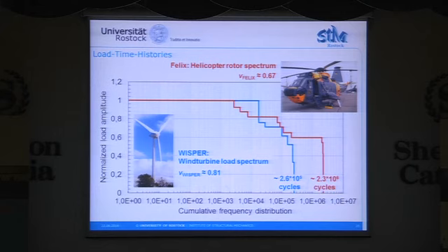And then we counted this with the rainflow method, and then we get such blocks within a restricted number of cycles in each block in order to have the block loading sequence for the ultrasonic fatigue testing system. Moreover, we have the wind turbine load spectrum called Whisper with a smaller number of cycles, and this is transformed to an R ratio of 0.